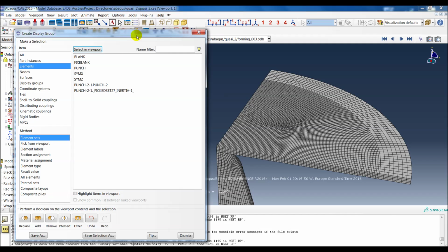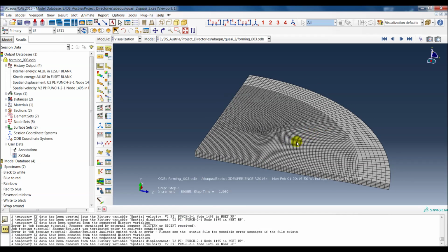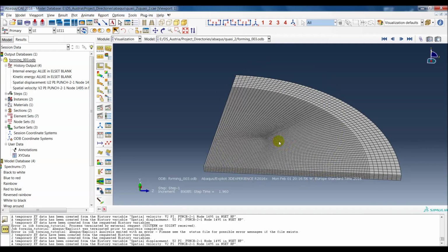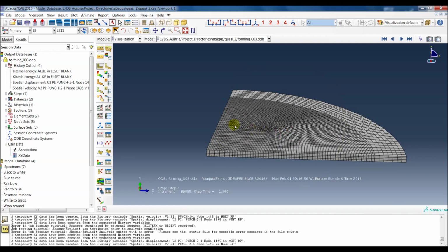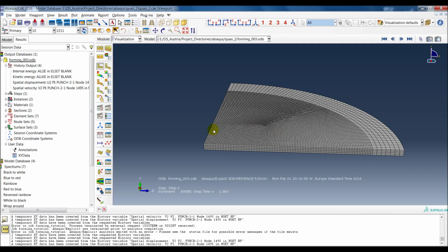Another thing we can check to see if there's any problems perhaps with volumetric locking in the elements is to check the pressure. Now, with very, very large deformation, typically we would see this in quadratic elements, where we end up with artificially high stiffness in the element.